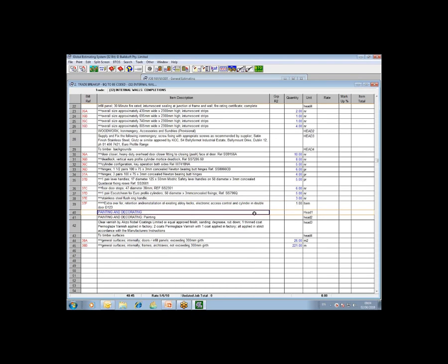Now, you'll notice that the last section here is painting and decorating. So naturally, what I'll want to do is send this section to a painting and decorating individual package. What I'm going to show you here is how you can use the rate build-up sheets to code multiple items into various packages, and then also, in the same section, internal walls completion, code an item individually to a different package. So I'm going to put this item, painting and decorating, to the painting package.